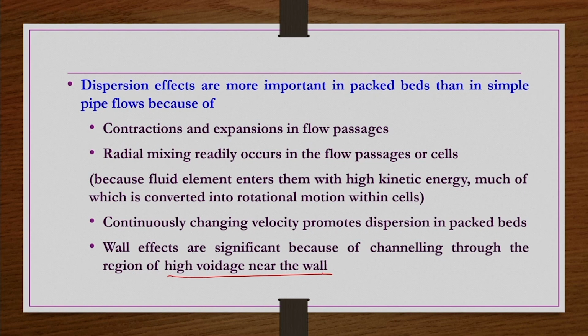Near the walls, usually the voidage or volume fraction is more. Actually, this voidage is also not uniform in the entire packed bed. If you take region-wise, overall volume fraction we take for engineering calculations, but if you are using especially regular non-spherical particles, then the voidage varies from location to location.